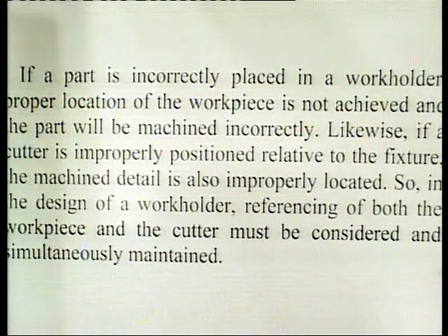So, if a part is incorrectly placed in a work holder, proper location of the workpiece is not achieved and the part will be machined incorrectly. Likewise, if a cutter is improperly positioned relative to the fixture, the machined detail is also improperly located. So, in the design of a work holder, referencing of both the workpiece and the cutter must be considered and simultaneously maintained.